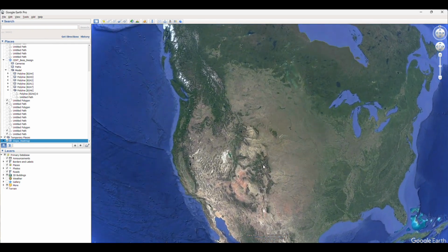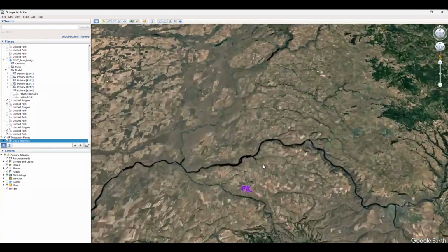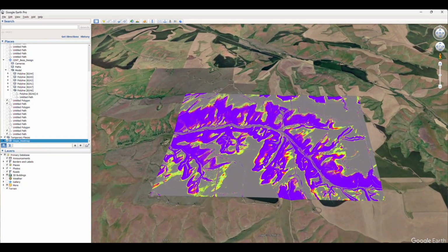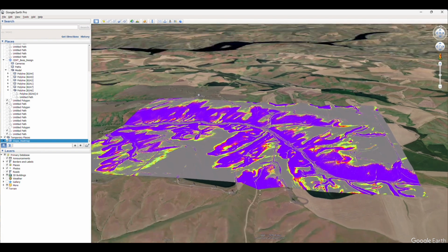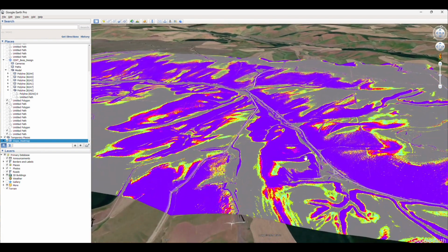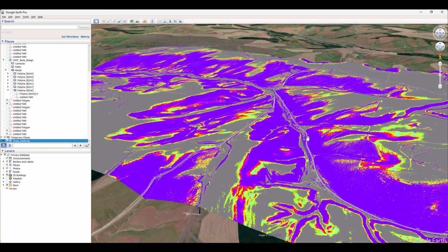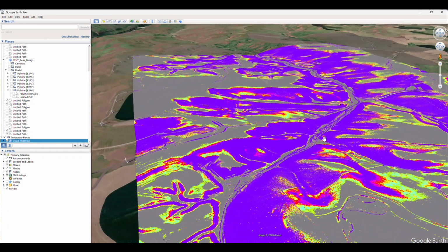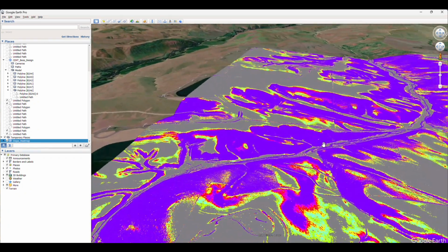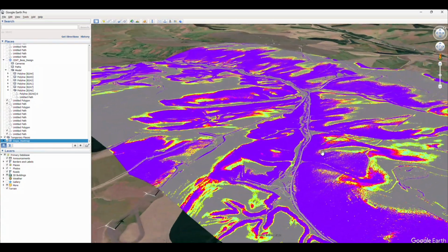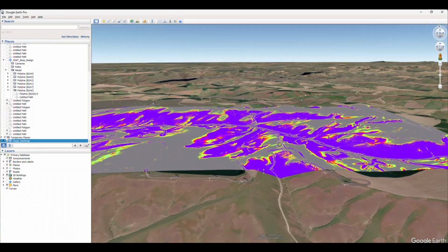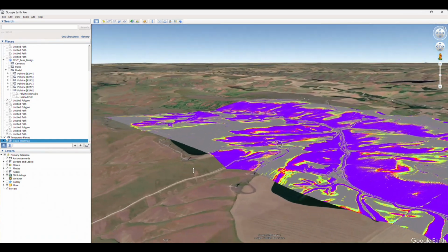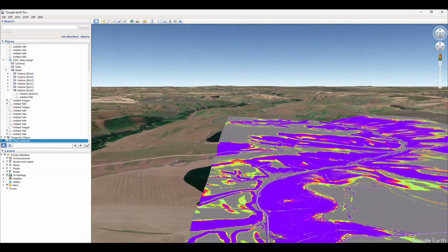This is very useful for sharing the slope heat map with team members who may not have Civil 3D or GIS software. One of the main advantages of this tool is that we can review the existing ground slope without using Civil 3D. Using only the GeoTIFF and DXF boundary, we can create a slope heat map, slope area summary, CAD output, and Google Earth KMZ output. This helps during early-stage solar design, racking system selection, grading review, and constructability analysis.